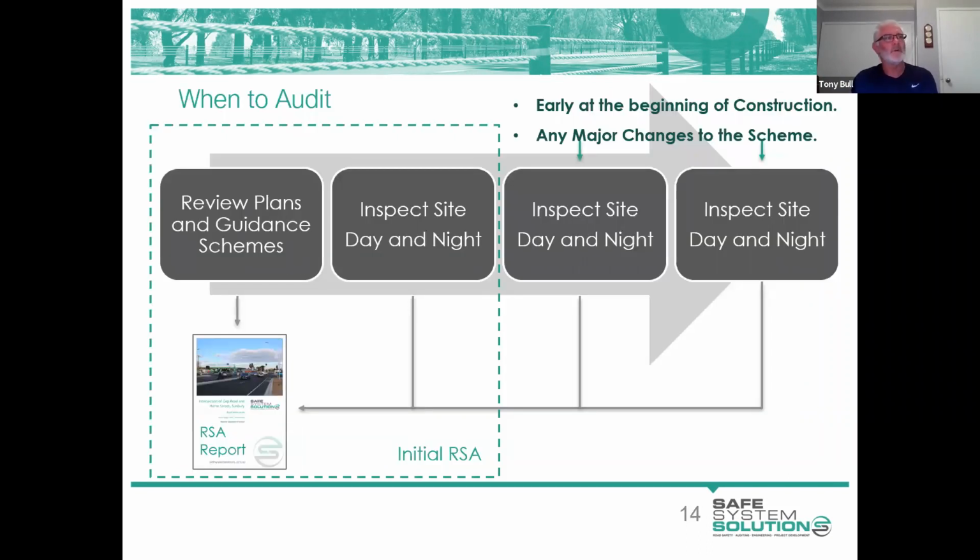All right, so we went to audit, and it's right across the construction requirements. We can review plans, we can do desktop plans, inspections, or not inspections, audits. We can make sure that when you're undertaking your on-site audit, and I see from this slide we've got day and night, day and night, day and night. It's so important that when you are undertaking a road safety audit, that you not only do the daytime audit, you do the nighttime.